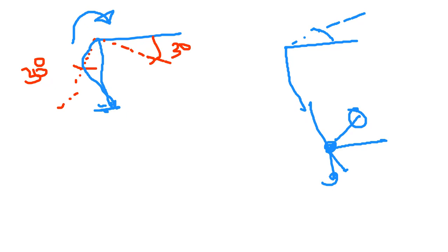The hinge will not restrict the rotation, but in the rigid joint, it will restrict the rotation. Whatever angular changes happen here, the same angular changes will happen at the other point, but that will not be the case with your hinge. You got me?